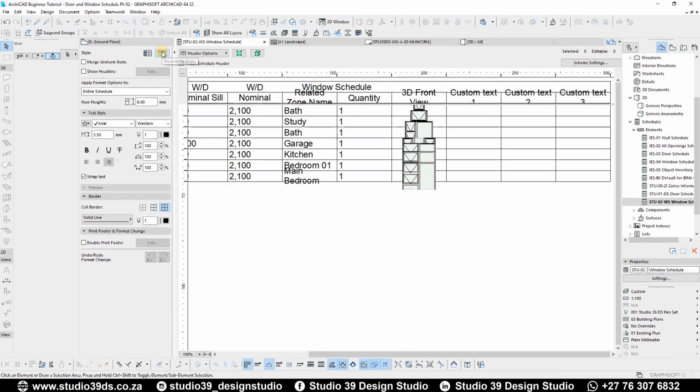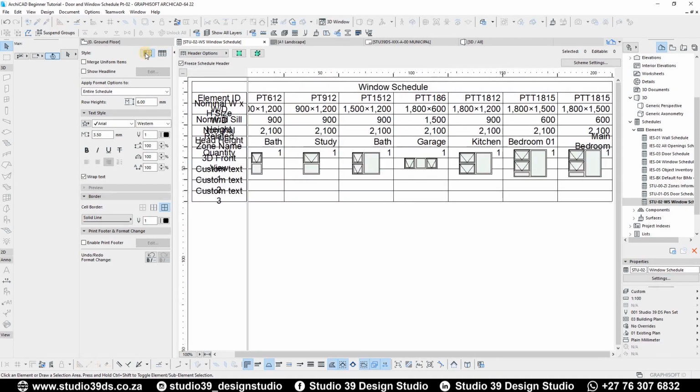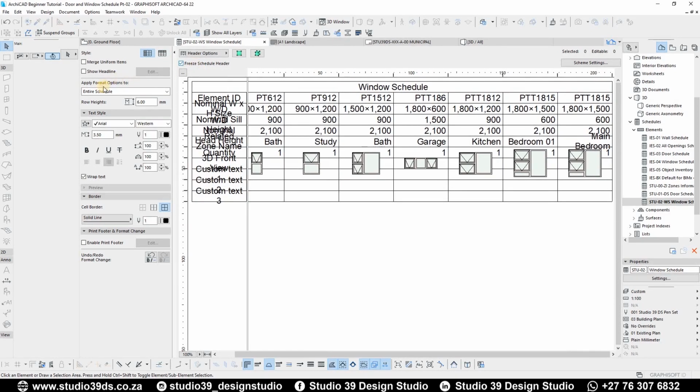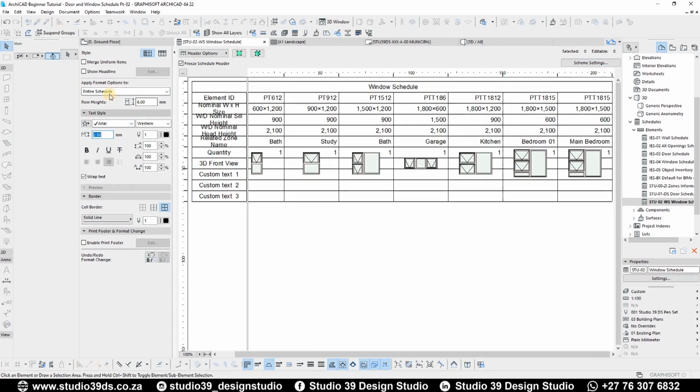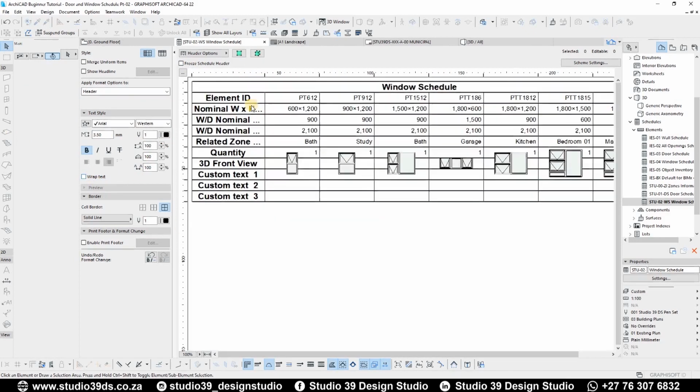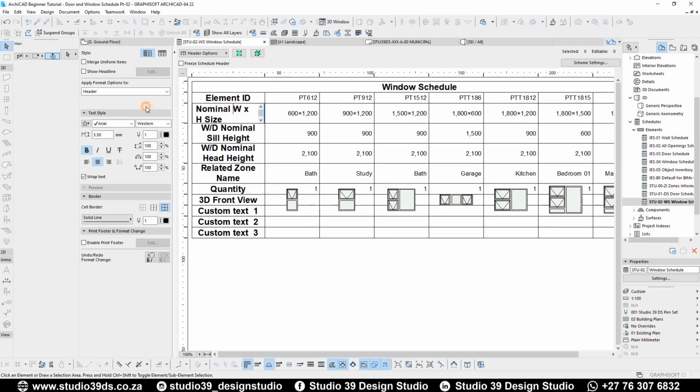It's going to be collecting information according to rows, but we want to collect in columns, right? And then you see that the schedule header is frozen. I want to start with entire model and then go ahead and make this 1.2. And then extend like this, like so. Text wrap, delete all of this unnecessary information. So I'm just cleaning up right here.